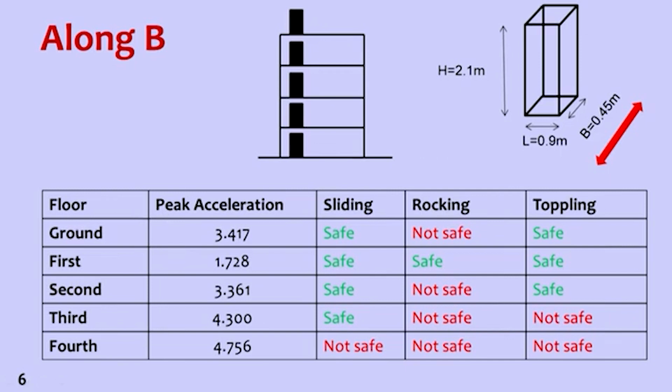We modeled this building as a framed structure, gave El Centro ground motion to it, and obtained the acceleration response at floor 1, floor 2, floor 3 and floor 4. For this we employed a numerical technique, Newmark's method.